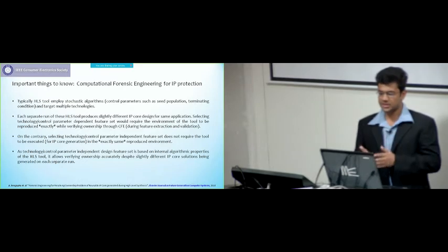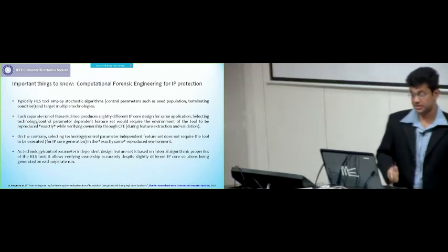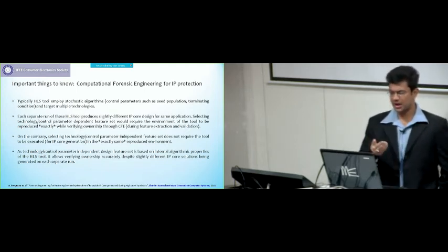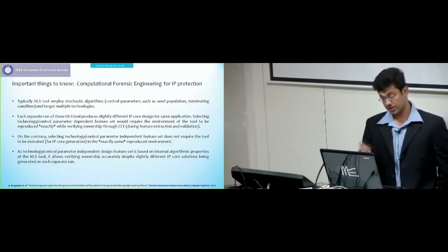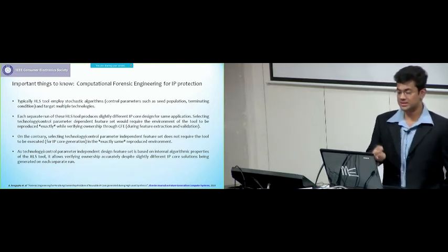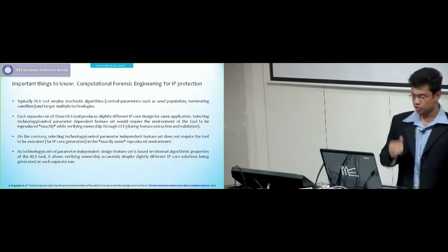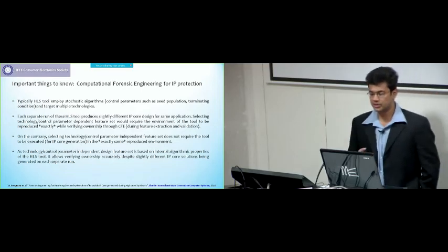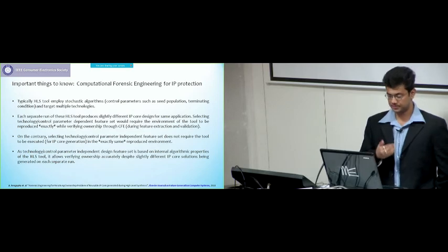When somebody wants to apply CFE for IP core protection, these important points have to be kept in mind. The first is, the HLS tool may employ stochastic algorithms that may have some control parameters such as seed population, terminating criteria, and may also target multiple technologies. So, each separate run of these HLS tools may slightly produce different IP core designs for the same application. So, selecting a technology or control parameter dependent feature set would require the environment of the tool to be reproduced exactly while verifying ownership through CFE.